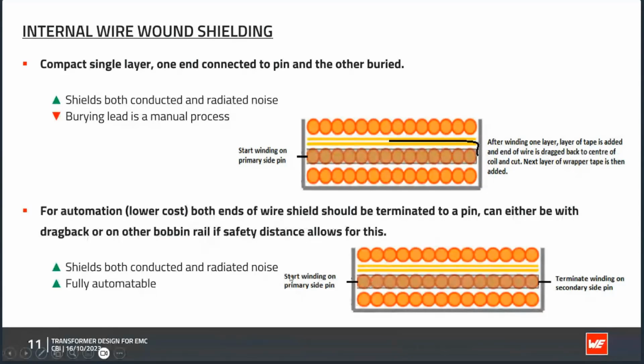So of course, everyone tries to optimize his power supply for the best efficiency, and every point of percentage counts. So definitely we want to use all the available winding space for the actual winding that carries the current, right? The primary and the secondary. So if not absolutely needed, we would try to skip the shield winding, and we only put it if the customer really requires it. Maybe the customer has seen EMI issues already, and of course, if we know it's needed, then we can put it.